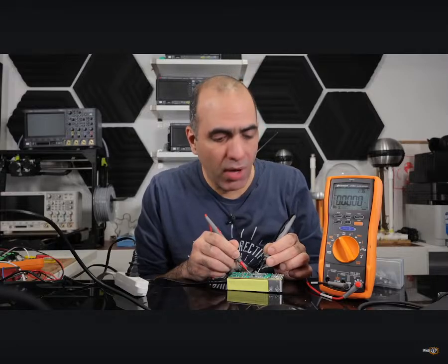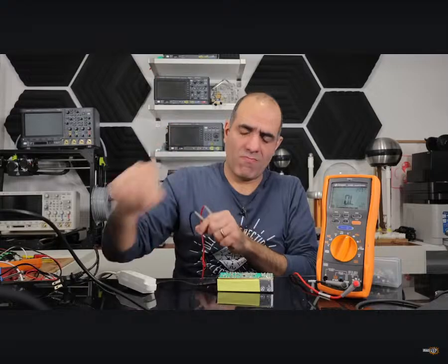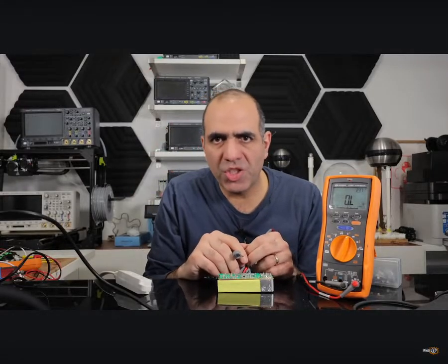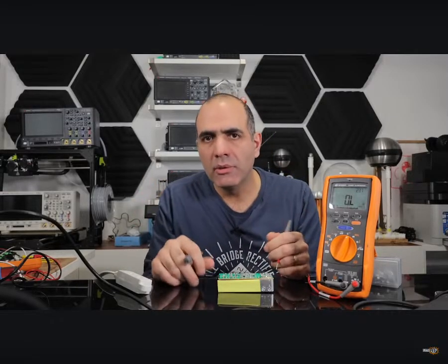For some reason the supply voltage to the chip is 0. I wonder. Look, the chip supply line is shorted to ground, which means the control chip is broken. It didn't die a natural bulging death, you know.